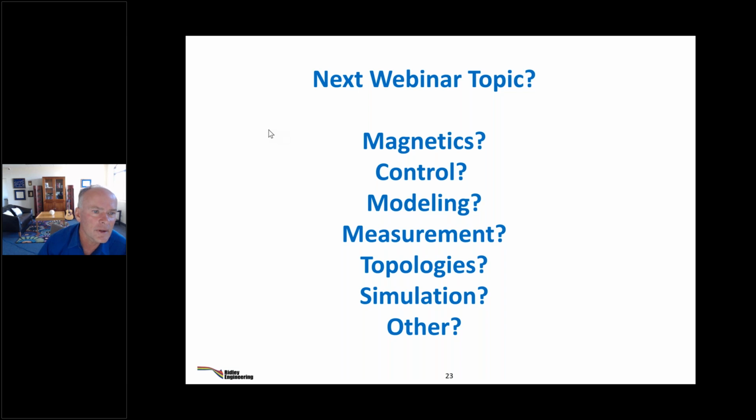Low voltages, yes. GaN FETs, yes, you can use GaN FETs. Is there a minimum load? There's lots of papers on light load for LLC, doing PWM modulation as well. If one wanted to design an LLC for 400 kilohertz on 100 kilowatts, I don't know why anyone would want to do that. I think you'd be nuts to design 400 kilohertz on 100 kilowatts. Maybe you've done it, but no, at 100 kilowatts you're not going to switch at 400 kilohertz. It's just not going to happen, in my experience.